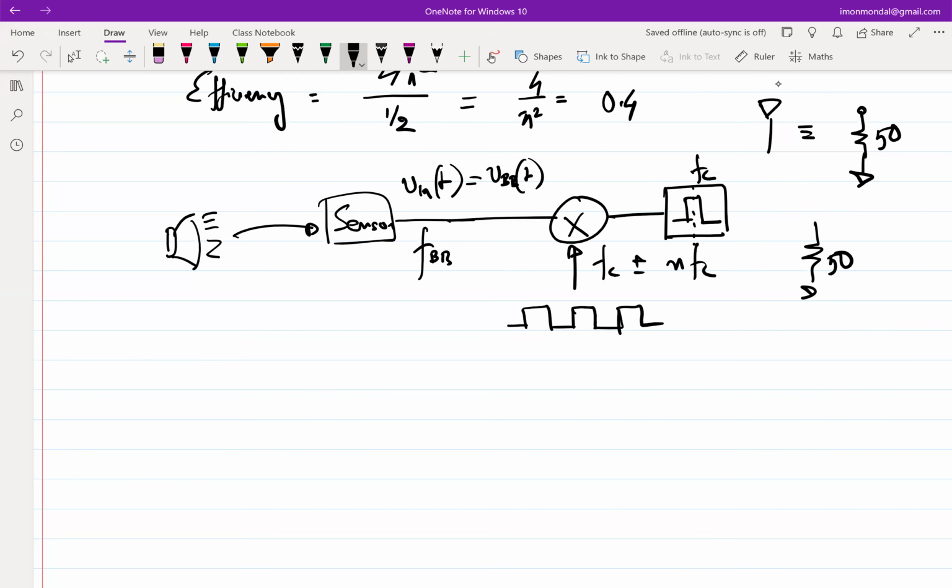Again, this is not a pulse in time domain. This is a bandpass filter. An ideal bandpass filter, again, doesn't exist, but the simplest bandpass filter you can think of is an RLC filter, right? So let's go with that. Let's assume you have some attenuation at out of band frequencies for n·fc, and only fc translates. Fine. So now we have only fc here, and the others are negligibly small. And then I connect it here, right? So now the question is, will it work?